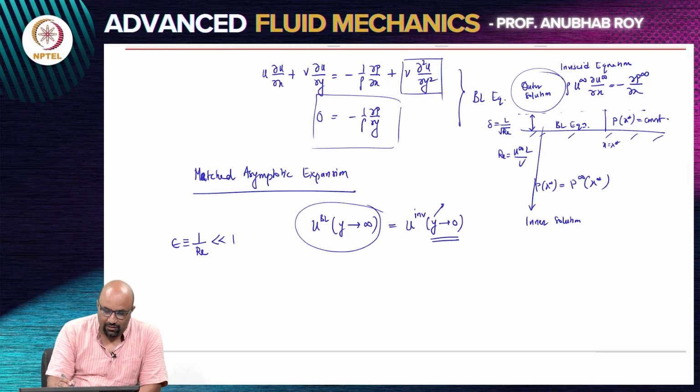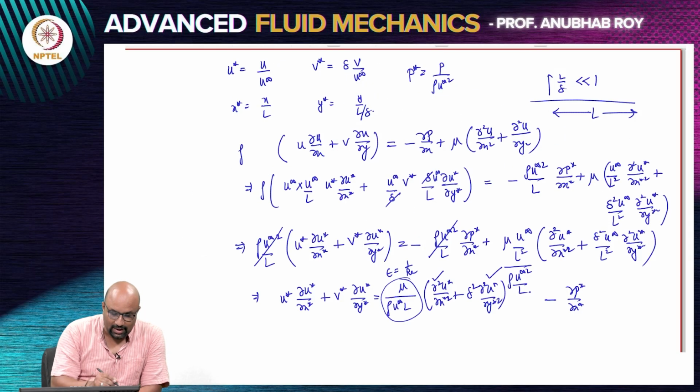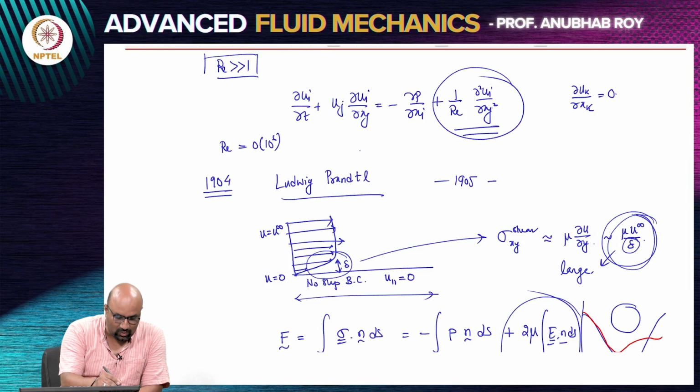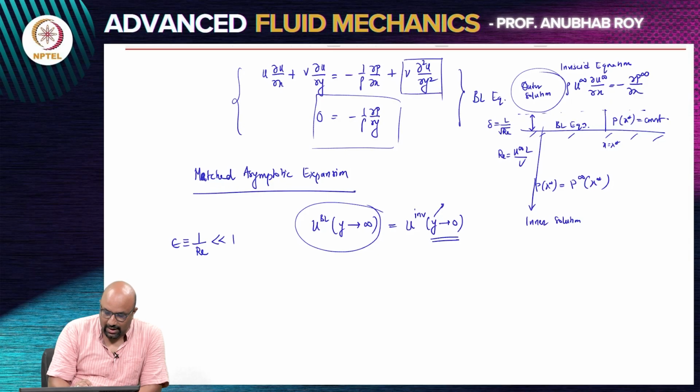So, what we will focus on is primarily working with Prandtl's boundary layer equation, which, as I said, is the leading order description. Obviously, we dropped terms that were present in the equation. If you remember, in the derivation that we had, we finally arrived at an equation which had a 1 by Reynolds term and a 1 by Reynolds square term. All those terms were effectively dropped from the equation. So, this is the leading order description that you get for Reynolds going to infinity.